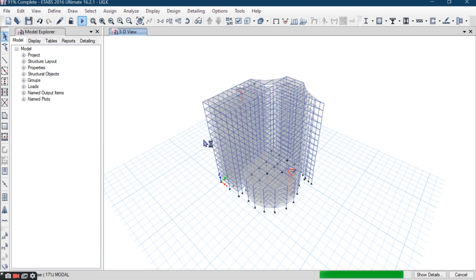Then we will see if it is failing in the displacement also, on the wind load I have planned. I will see if it is failing in the displacement or not. So you can check that by H by 500. It is the formula for checking the vertical displacement, H by 500 for the wind load. For the earthquake load, H by 250. For the deflection, you can check the span by 250. For the long-term deflection, you can check the span by 350.